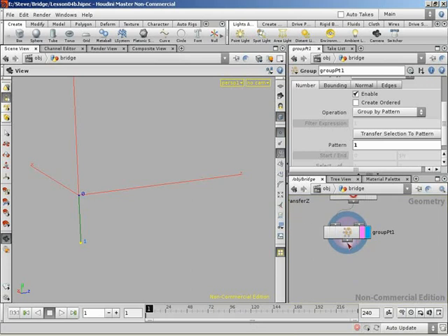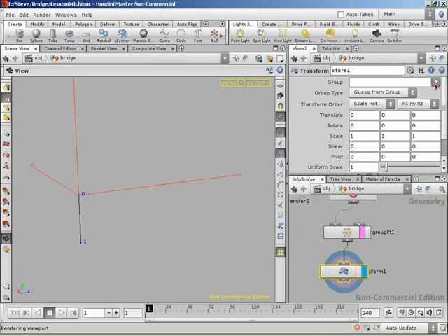And then we can wire this into a new transform node. And with this transform node, we are able to specify a group to work on. We'll work with group 1, which means that now when we translate in Y based on our tier thickness, we're only going to be affecting that single point. So we can take our translate in Y and set that to master control, tier thickness. And that will offset that point based on the thickness of the tier. So the curve is now basically the height of the gap between the bottom of one tier surface and the top of another tier surface.